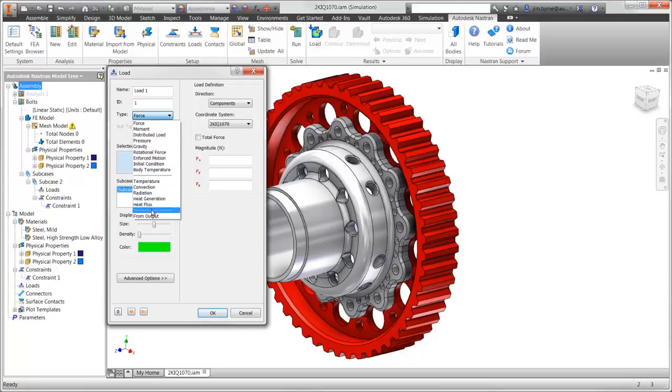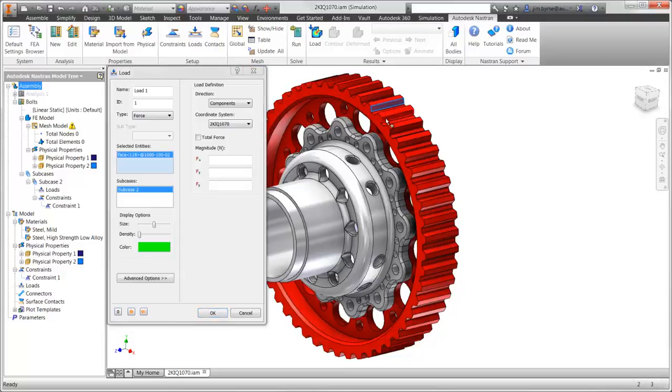Use options such as force, pressure, moment, gravity, centrifugal force, and prescribed displacement. There are also loading conditions for thermal studies, such as heat power or prescribed temperatures. These loads can also be described with variable distribution for hydrostatic scenarios or bearing loads.